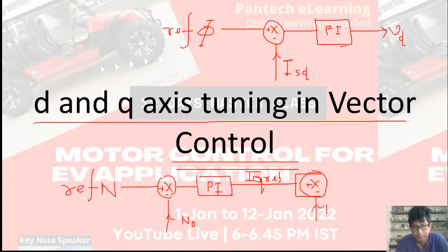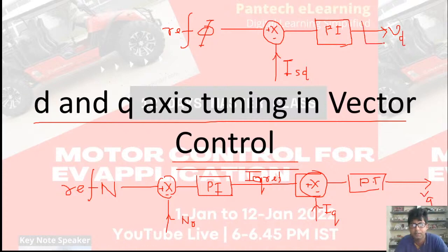This is coming from the quadrature axis current of the machine, which is again coming after the ABC to DQ transformation. Then it is going to one PI regulator, and then it is generating the quadrature axis voltage reference. Even everywhere there is some limiter. Limiter is there everywhere.